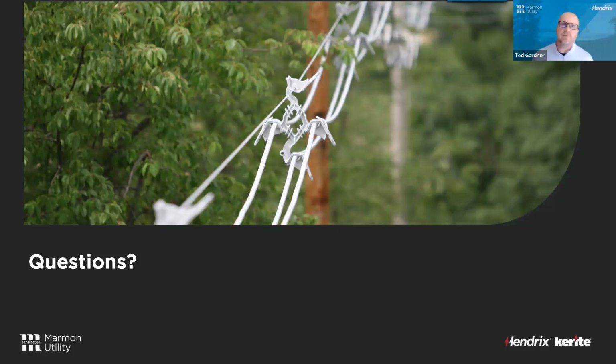Yeah, I understand that's what ADSS kind of promotes. What we're looking at is typically a worst case scenario. When it comes to spacer cable, we really focus on the messenger, and we take the added weight of the phase conductors and the spacers themselves, and we have an idea of how much surface area they'll tend to pick up.